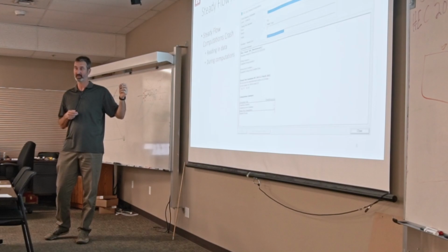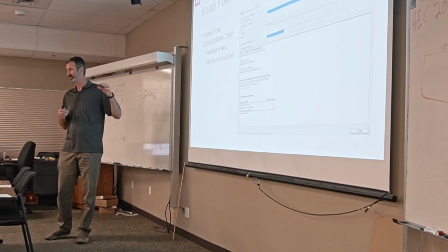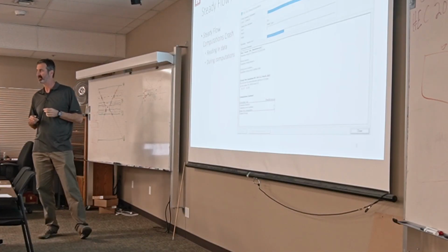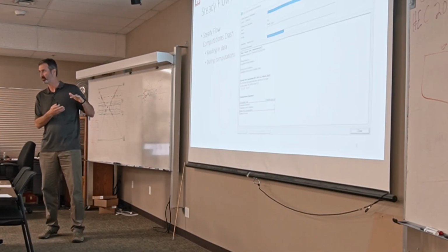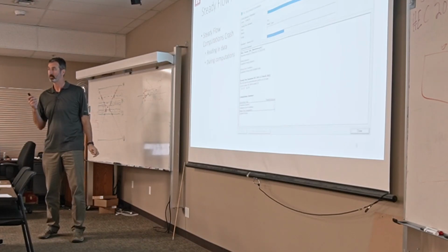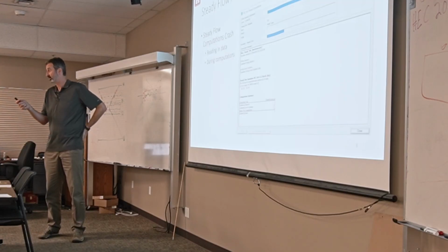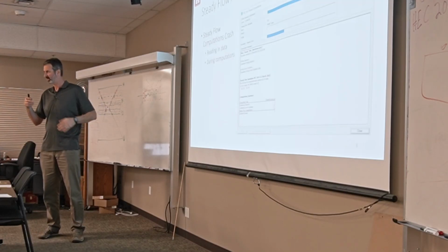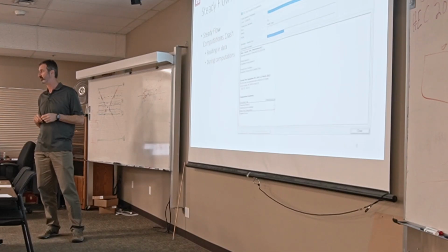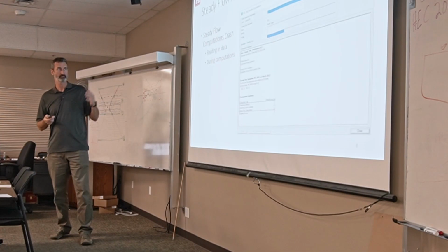Most of the time, there's a bridge either just upstream or just downstream of that cross section, because cross sections are pretty solid. There's not many instances where just reading in a cross section will make the program crash. It's usually a structure. So when it crashes reading in and it tells you a location, go look in that location. But if you don't find anything, go look a little bit above and a little below it too. We haven't had problems like that for a long time, but they still could be there.